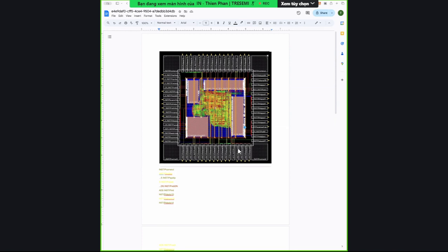It looks like a lot of students are having the same issue. I think just review the macro placement and try to optimize it. Shove the macros into the corner. Essentially, don't have tiny gaps around the macros.